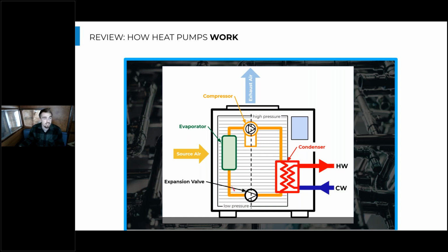So there's constantly refrigerant being pulled out of this side of the loop and compressed into the high pressure side, and then it's trickling back to the low side. So you can see we have this clockwise flow here where we consistently have refrigerant flowing around the loop just through the act of the compressor pressurizing one side and then trying to reach equilibrium by trickling back to the low pressure side on the other half of the loop. And so why is this difference in high pressure and low pressure important in the refrigeration loop?